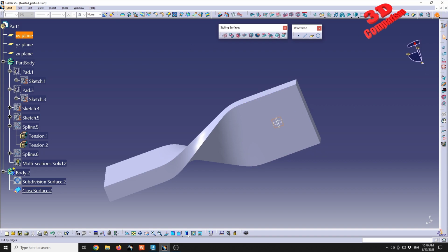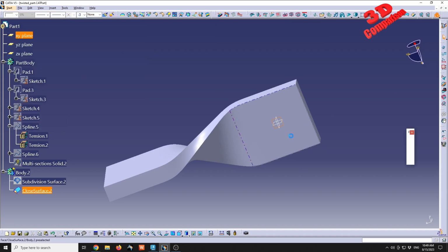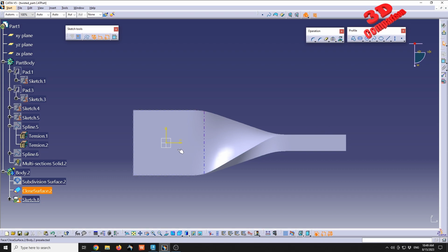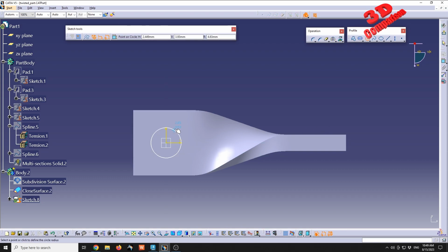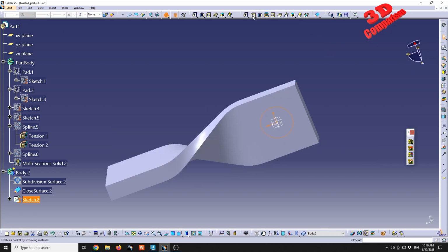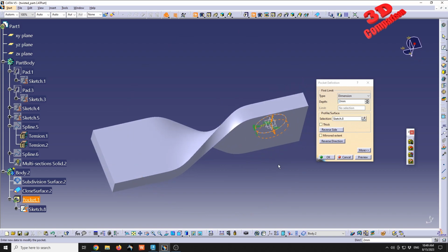We can now have this transferred back to part design, and over here I can select and define those circles. So we know that they had a radius of 5. We can have those cut. So mirror extend that.